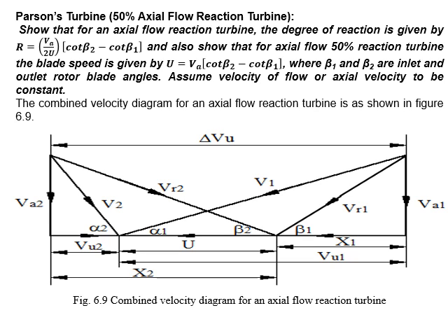Coming to the exit velocity triangle, here x2 distance is taken as, if you consider this velocity triangle, cos beta 2 equals the ratio of x2 by VR2. That means the distance x2 equals VR2 cos beta 2, as well as cos alpha 2 equals V_U2 by V2.